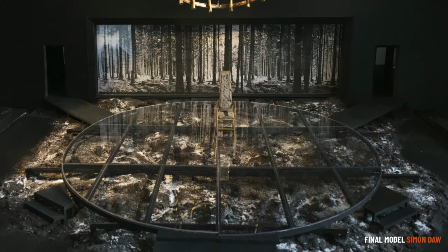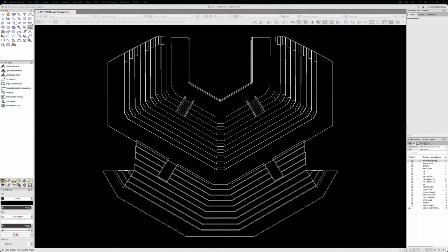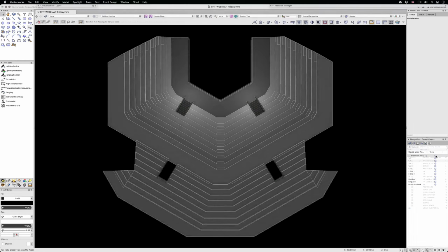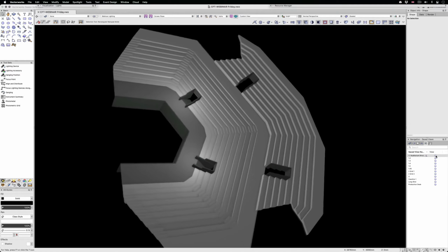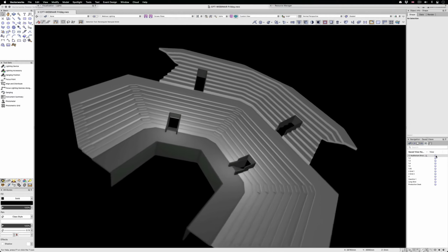My main concern was the way the glass would reflect any low-angled light into the audience. I wanted to check these angles to make sure that the audience were not caught by stray reflected light or constantly bothered by the reflections of the lighting instrument lenses. So I went about building a simple model of the auditorium and stage to check some key angles in order to make sure that Simon could keep going with his design.